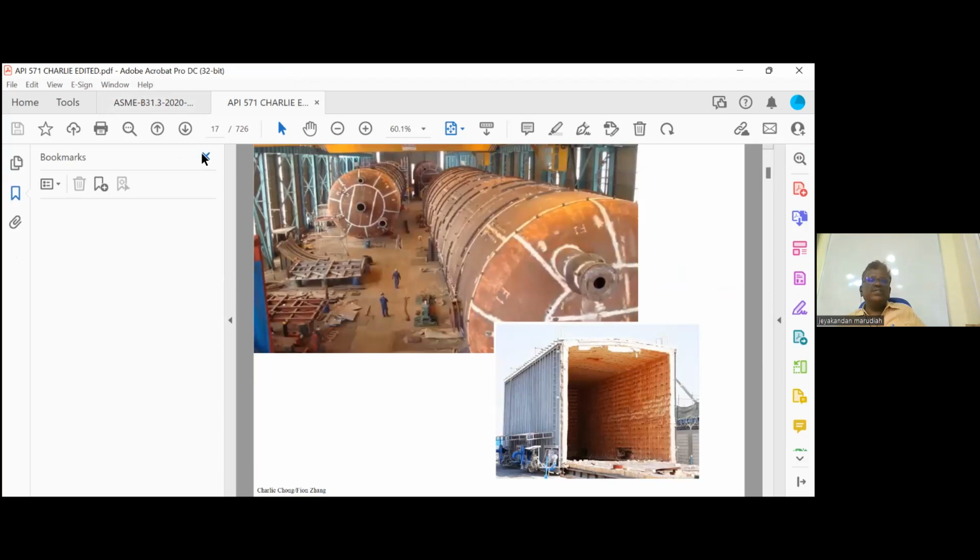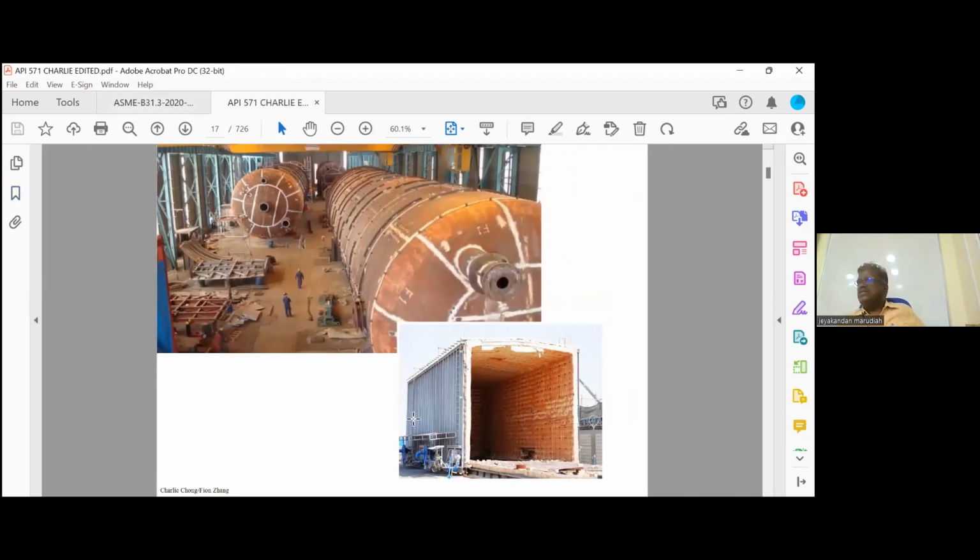So this is called a furnace. In a furnace, inside you can fabricate the spools, keep the pipes inside, many pipes inside, and close the furnace, and you can do the PWHT. In PWHT, what you are doing is slowly heating, holding, cooling. That is the PWHT. Then suppose a pipe is a lengthy pipe, it is not completely going inside a furnace. For example, the pipe is very lengthy, so for example, this end is outside. You can cover it with insulation, do the PWHT here, then take the pipe and reverse it like this. But there should be at least 1 foot overlap with the portion which was previously inside the furnace, again going into the furnace.